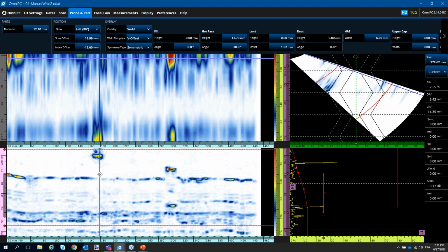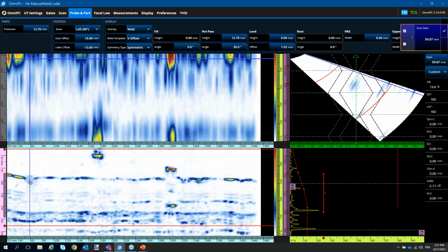Now, how many indications are there? I see 3 obvious ones. I see something going on here that breaks from the geometry line that the C-scan, well, I wouldn't say so very clearly. That could possibly be porosity just looking at the signature. So I'm still looking for anything that stands out. Obviously, I'm back with that OD crack. And now I have another root location indication to review. Possibly a little bit of indication, so I need to make sure there's nothing. Okay.